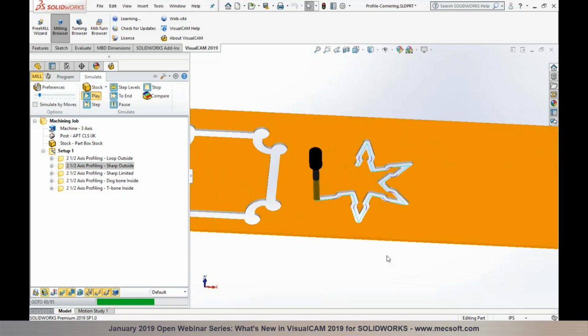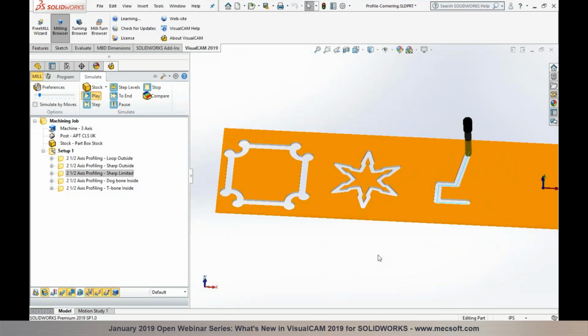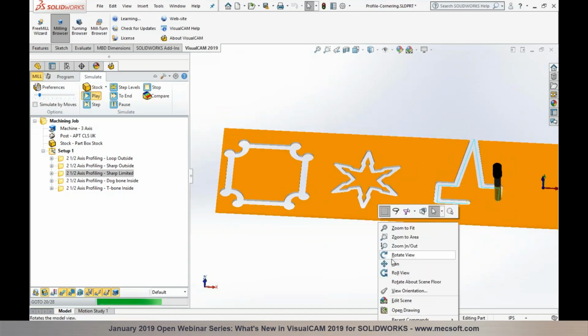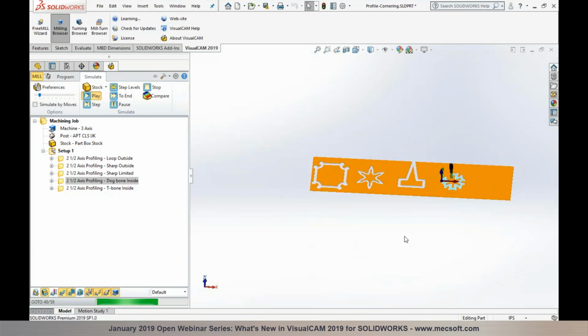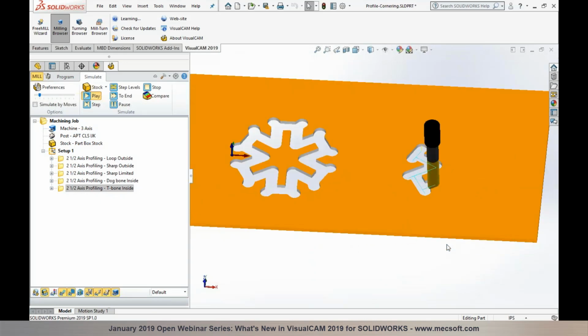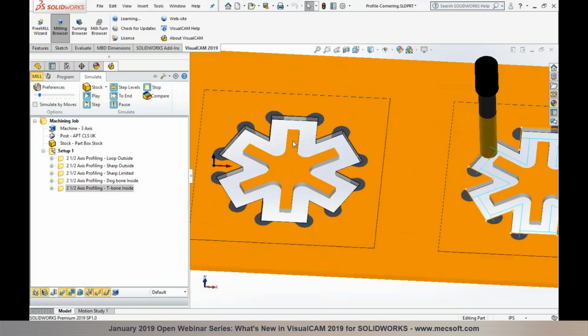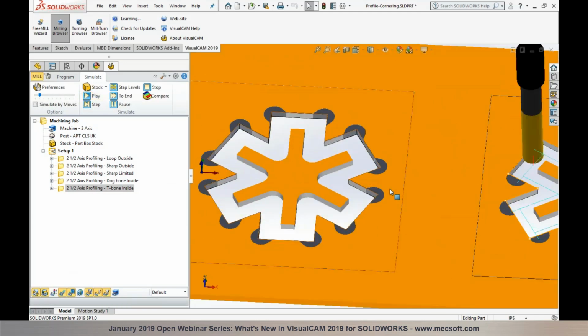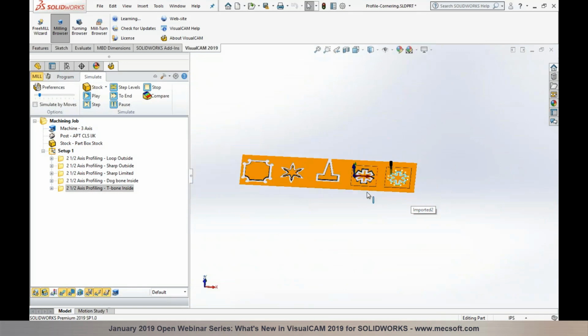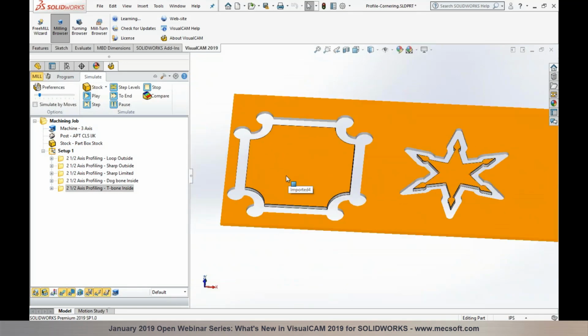These cornering options were put in for a variety of reasons. Some of the sharp corner options, T-bone and dog bone, are more for the woodworking joinery industries, where you have 2 pieces that need to be joined, and the male portion or the female portion has to be cleared completely so the male portion can sit inside. And then some of the looping functions can be used in flame cutting, laser cutting, and things of that sort.